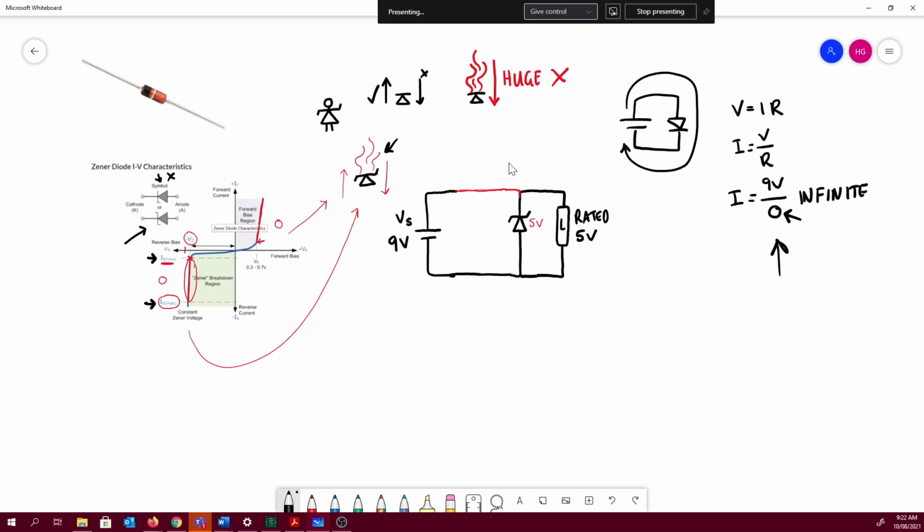So how do we control current? How do we make sure that the current flowing through this diode is stepped down a little bit? Beautiful. Yeah, we just add a resistor. And so you should always see, if you want it to work, a series resistor in line with a diode, with a Zener diode rather. You should probably see one in with a diode as well, but whatever.